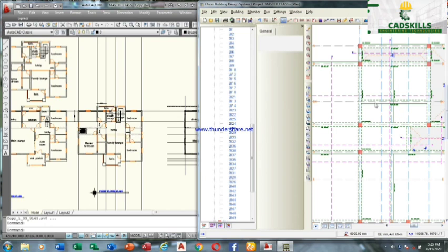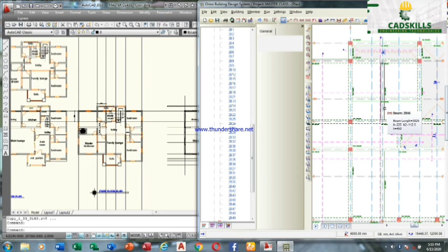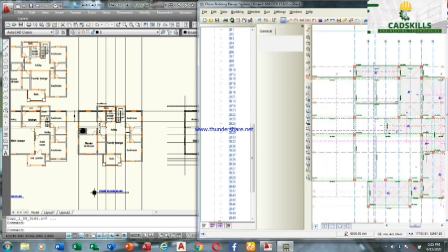Ask you whether you want it to be secondary beam or primary beam. So this one continues to this one. Yes, continues to this one. From here it is supposed to be open. It cannot be open like that because there must be a wall, there must be a beam here to hold this slab landing here. So we'll leave it like this.